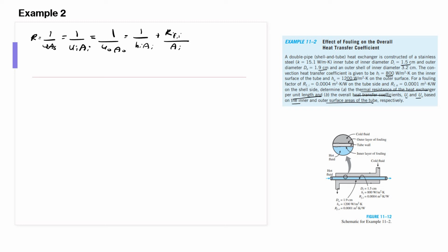So in this question, we consider both fouling factor inside and outside. Sometimes in a question, maybe they will mention the outer part fouling factor only. So that one you need to only calculate the outer part. If the question asks you to consider only the inner part, then you need to calculate the inner part only. So it depends on the question.